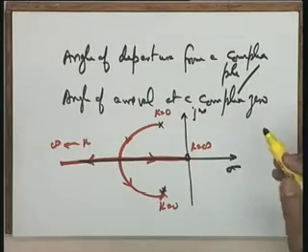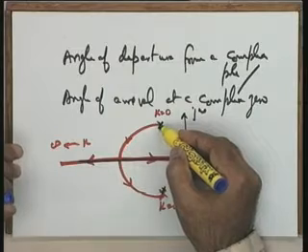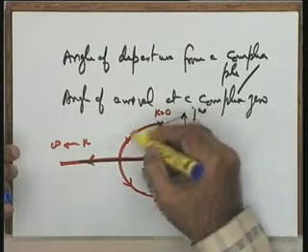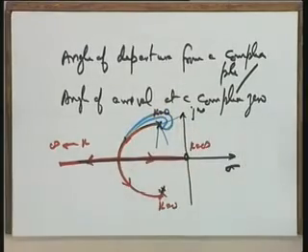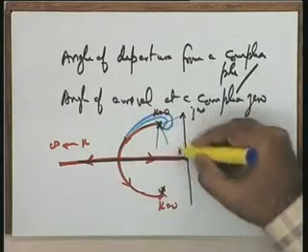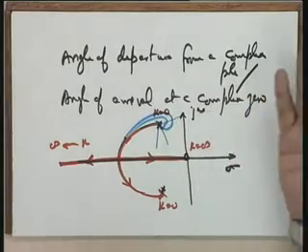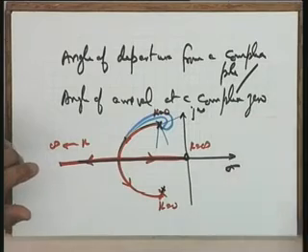So if it is a circle, you can easily make the root locus diagram. But otherwise, in general, you will very much like to know: when the root locus leaves this particular complex pole, does it leave in this direction, this direction, or this direction? It could go this way, or any direction it can take in general. For this particular numerical example, you can prove that the complex root branches are circles, and hence you don't need the direction. But since I have taken this very example, let me exemplify the direction through this example itself.